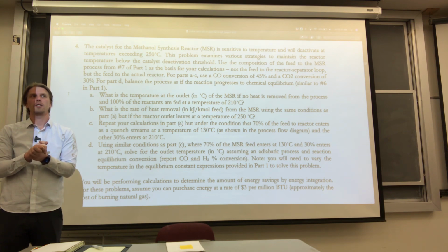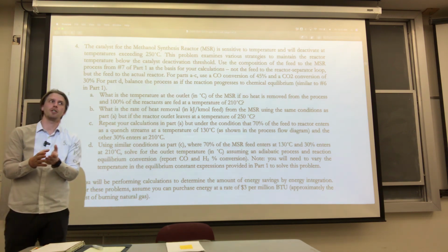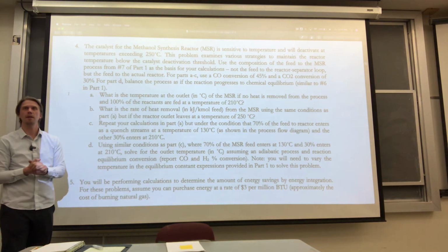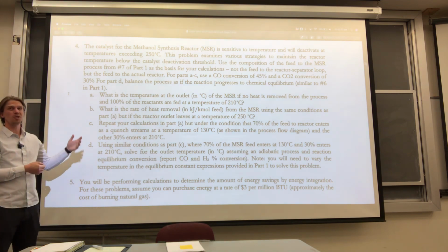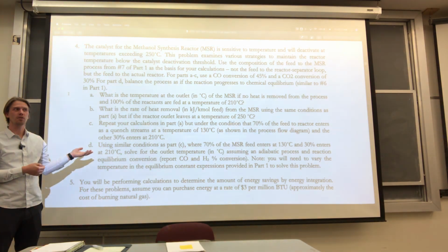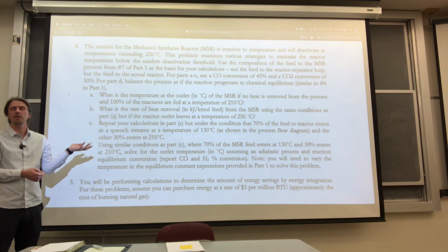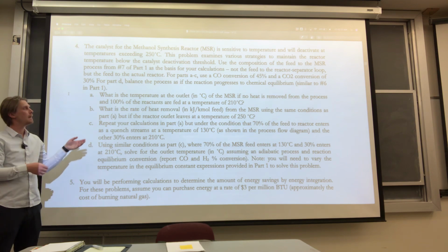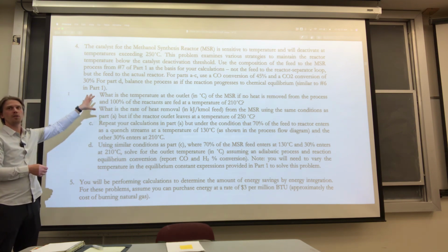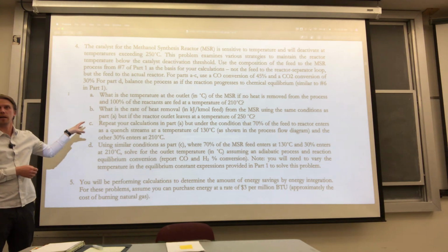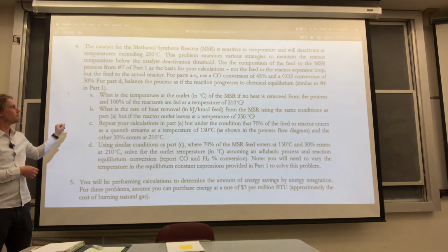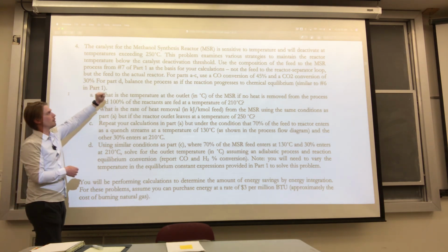And replacing catalysts is going to be on the order of millions and millions of dollars for a large commercial reactor, right? You do have to change them every once in a while because you get buildup of contaminants and byproducts. If you have sulfur in your methane gas stream, sulfur is a well-known catalyst poison for most materials. So that's why it's very important to sort of baby your catalyst, right? It's a very expensive workhorse in a chemical plant. So that's what all this description up here is.